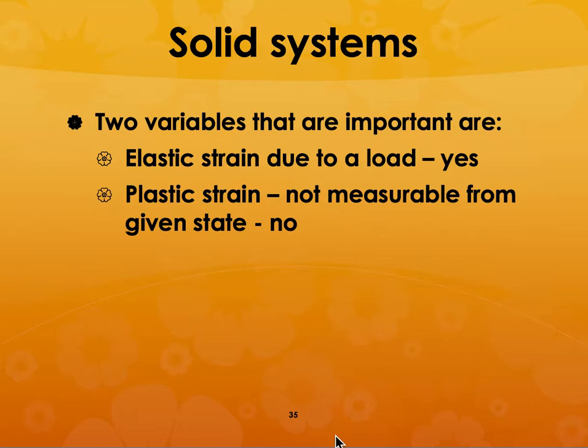You do not know where in the tensile stress strain curve you are. So it will be very similar to driving time to class. Okay, so the same way, your plastic strain that you have introduced is really not constant. So because of that, plastic strain is not a state variable, but elastic strain is.